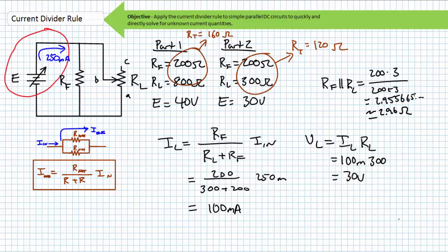However, with such a low total resistance, the output voltage doesn't need to be nearly as high as it was previously. In this case, an output voltage of only approximately 738.9 millivolts, or 0.7 volts, would be necessary to push 250 milliamperes through the parallel combination of a 200 ohm resistor and a 3 ohm resistor. This method is utilized by current limited power supplies to keep current below a certain preset maximum and limit the power dissipated by a circuit.